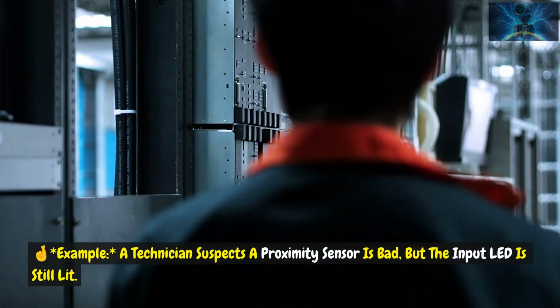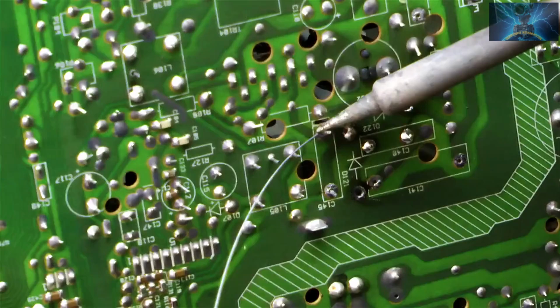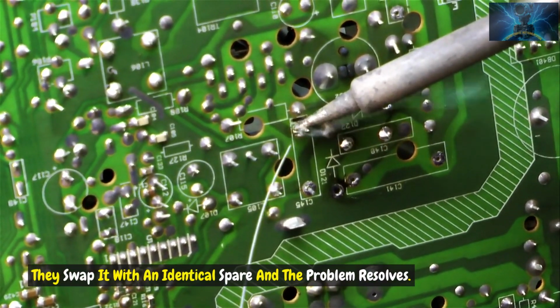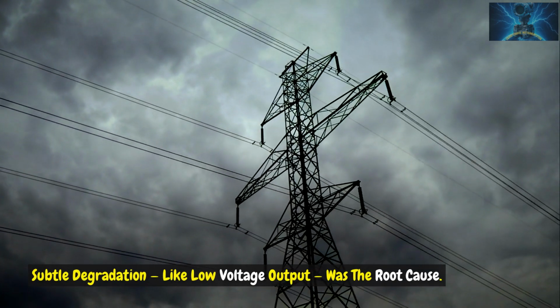Example: a technician suspects a proximity sensor is bad, but the input LED is still lit. They swap it with an identical spare and the problem resolves. Subtle degradation, like low voltage output, was the root cause.